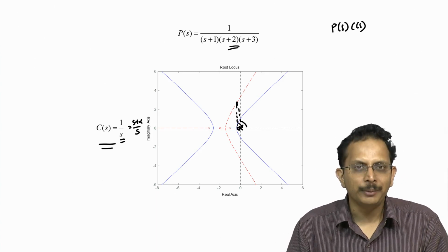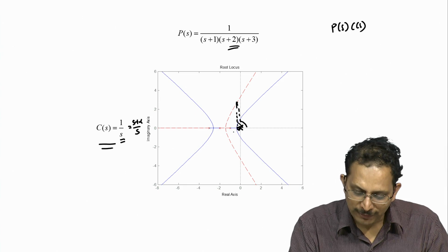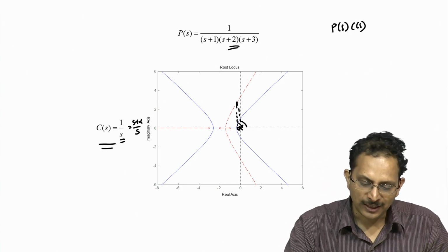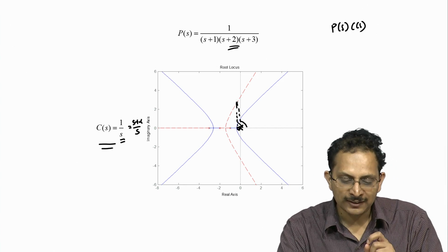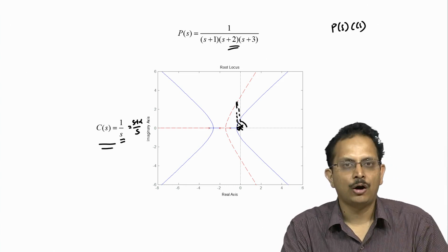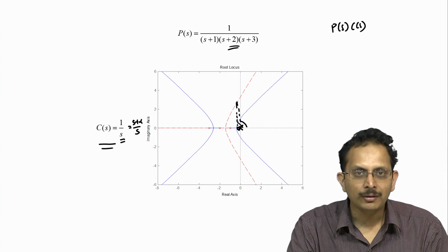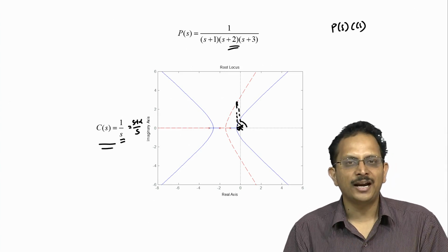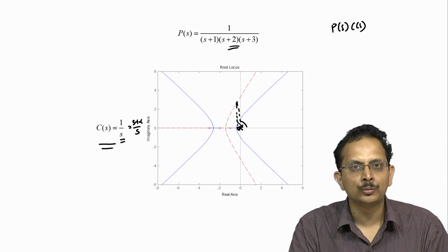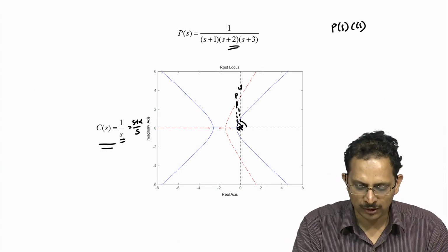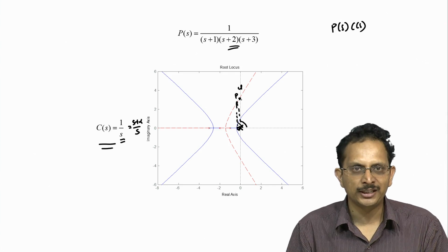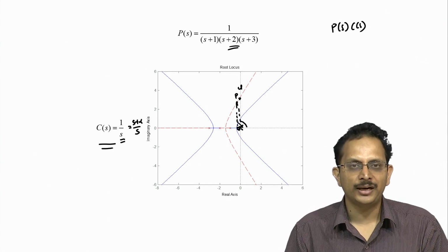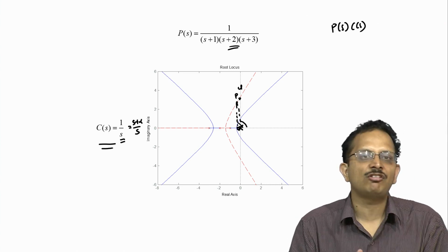What this essentially means is that if we choose a pole-zero pair that is very close to the origin, then that pole-zero pair will not affect the overall phase of points on an already existing root locus. So, if already we are getting the net phase of our open loop system at some point PCL naught to be equal to minus 180 degrees, the phase because of this combination of pole and zero will not be very different from minus 180 degrees.